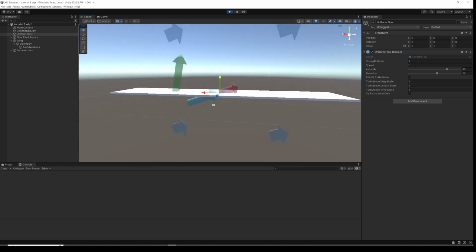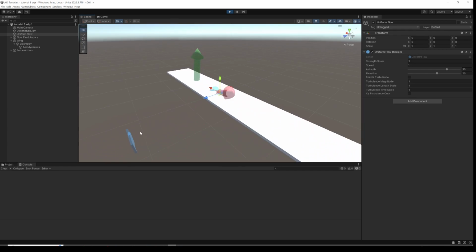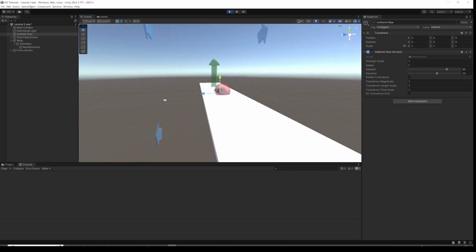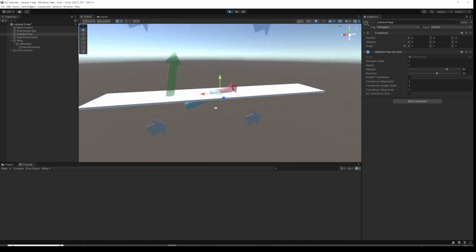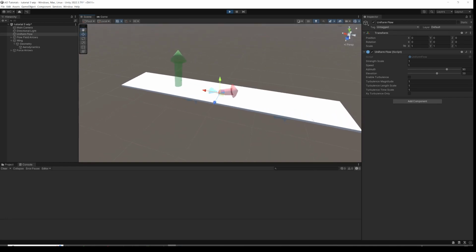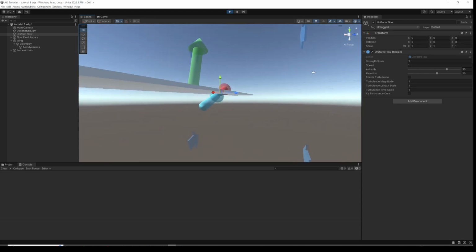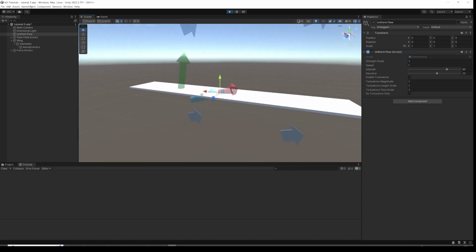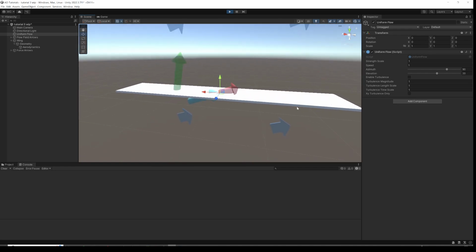And so imagine this is a ruler someone's chucked in the classroom, they've kind of thrown it, it's sort of flying at an angle like that, but it's like a really thin wing, so it hasn't really got any wingspan to it at all. It will still produce some lift and quite a lot of drag, and Aerodynamic Objects is happy with that, given the shape of the wing, the angle of attack, the angle of side slip. The lift model will calculate a reasonable approximation of what the lift would be. So if that really was a ruler flying across the classroom, this would be a fairly decent estimate of what the lift and drag is on there. And we can carry on all the way around, and then we're kind of back to where we started, just going backwards.